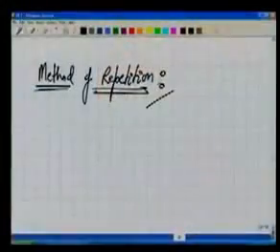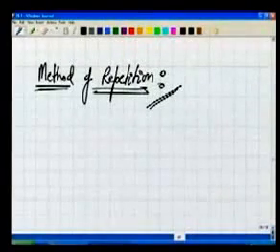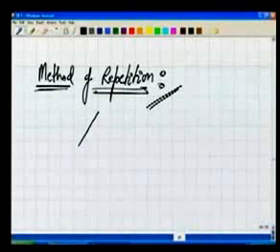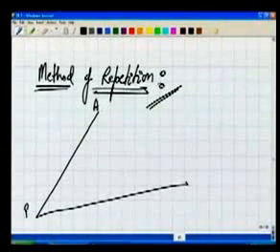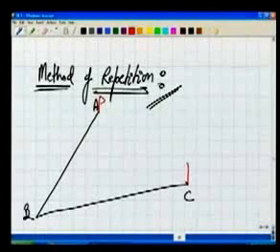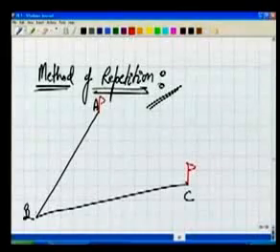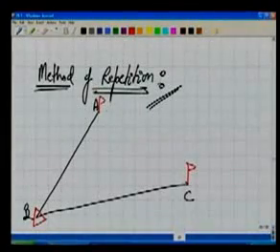What are the methods of measuring the angles? There is one method which is called method of repetition. First we will see how to measure one angle using this particular method. Basically, well, the job is, as we have been doing always, we have A, B and C. There is a ranging rod or some object at A and C, and there at B we have our survey station. A and C are the ranging rods, and we want to measure the angle ABC.